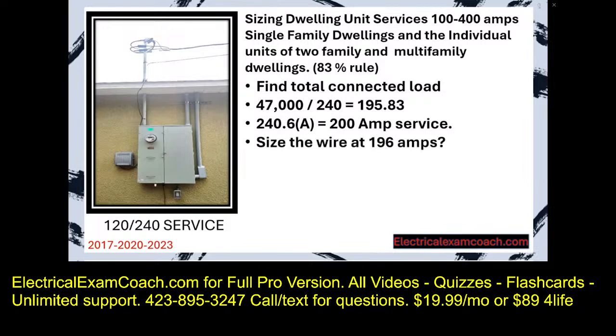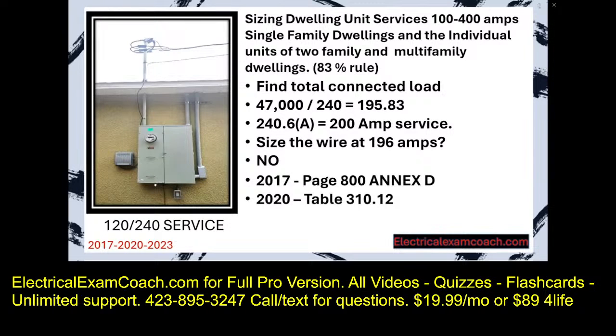Now the next step normally would be to size the wire at 196 amps, right? That's our known load. We can just follow our normal ampacity rules. Well, not with services that are in between 1 and 400 amps. And let me show you what I mean. Let's all head to page 800 if you're in the 17, this table if you're in the 20, and this table if you're in the 2023.